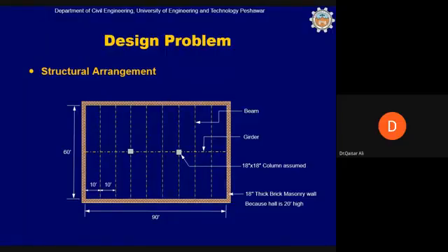If you look at this figure, this beam is supporting these two beams, so it is named a girder, though from the structural point of view it is the same as a beam. There is no difference structurally. It is only to differentiate that this beam, which is stiffer and stronger than these two beams, is supporting them, and so it is called a girder.